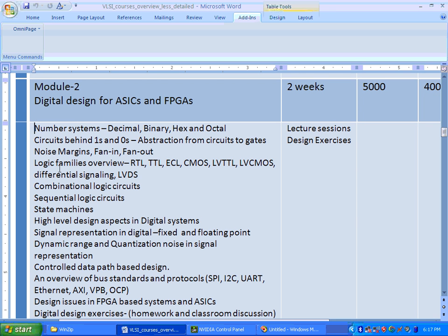Okay, so the ADC, let's assume 8 lines are coming to your FPGA pins. If you look into the ADC data sheet, it will be written that it is actually DDR lines, double data rate lines. So it means data is coming on both rising edge and falling edge. Now you should know how to configure an FPGA pin also in the DDR mode. You should also know what are the different voltage levels that the ADC chip is actually giving.